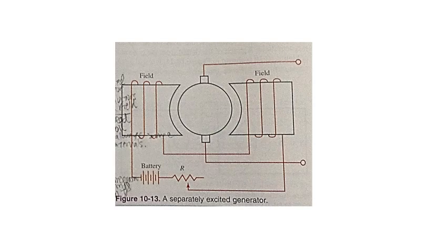Self-excited generators can be separated further into categories such as shunt, series, and compound. One feature that separates generators is the excitation method, the method that is used to start the generator running. Some generators require a separate power source during the starting of the generator. These are called separately excited field generators. Other generators use the generator's own leftover magnetism in place of that power source. These are self-excited generators.